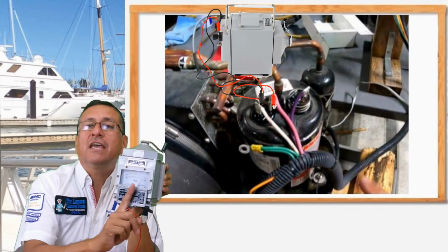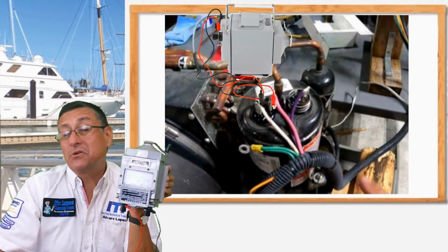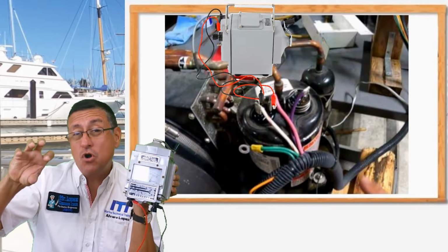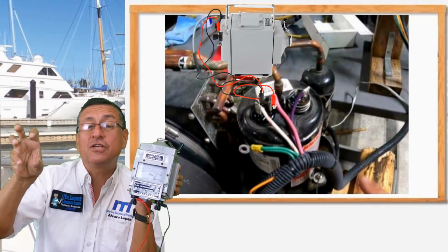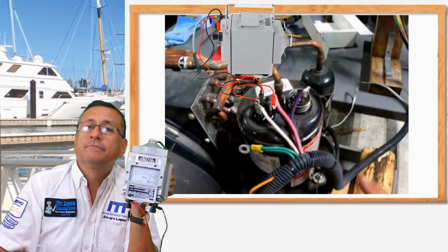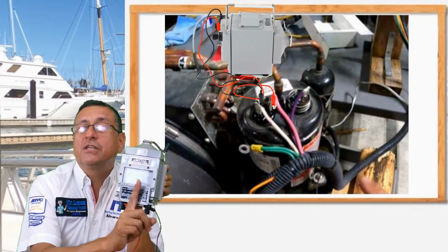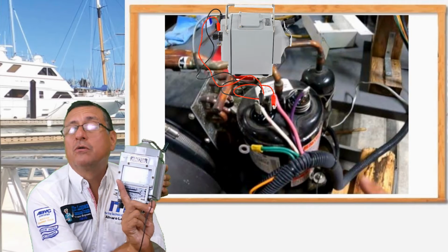If the needle stays in the middle, this is an indication that the compressor starts, but when you put more air conditioning, full air conditioning, maximum air conditioning, the compressor should die. In other words, it's not good. The needle should be pointed to 1000 ohms or more, infinite.